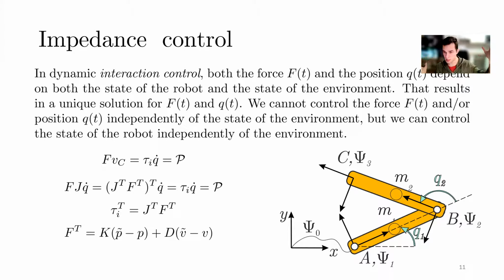If there is a gap between the actual position and the point where you want to be, it's like there is a spring there with a damper, and it applies force to the end effector such that it pulls the arm next to the desired point. It is the whole idea.